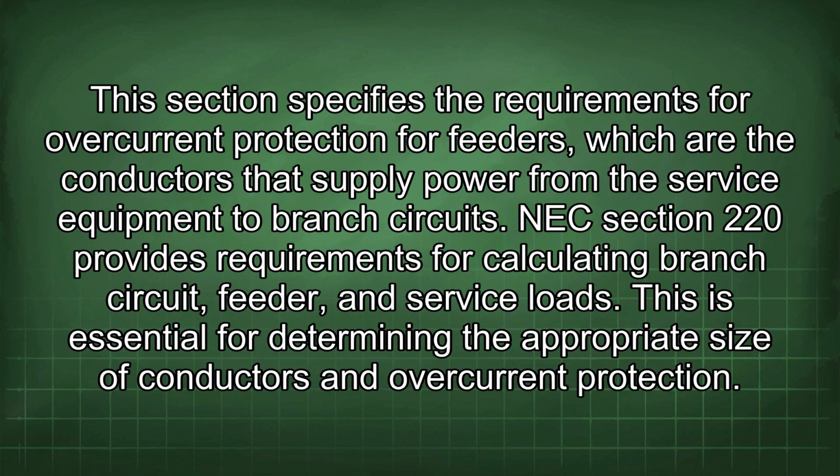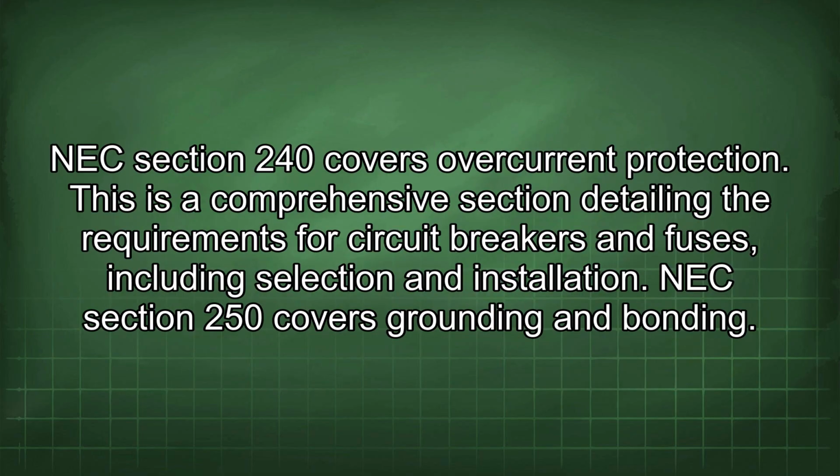NEC Section 215.3 covers overcurrent protection for feeders. This section specifies the requirements for overcurrent protection for feeders, which are the conductors that supply power from the service equipment to branch circuits. NEC Section 220 provides requirements for calculating branch circuit, feeder, and service loads. This is essential for determining the appropriate size of conductors and overcurrent protection. NEC Section 240 covers overcurrent protection. This is a comprehensive section detailing the requirements for circuit breakers and fuses, including selection and installation.